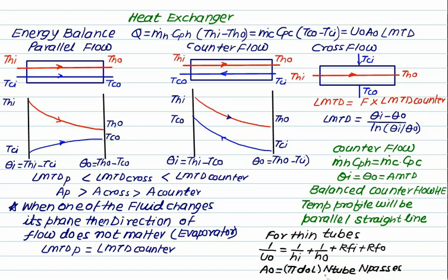For single tube you have to use 1, for single pass you have to use 1. If you are given the number of tubes, then do multiply to calculate the value of A0. That is the total available heat transfer area.